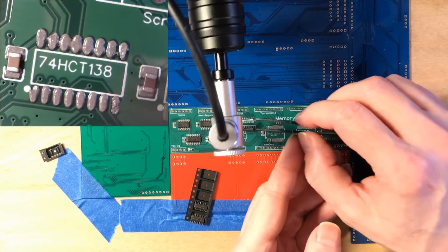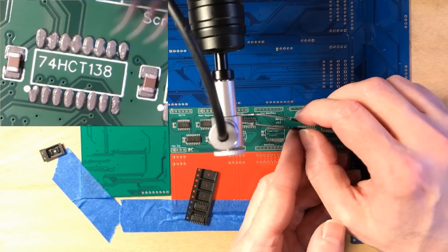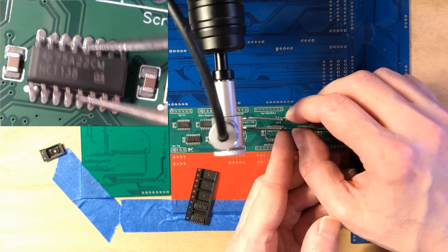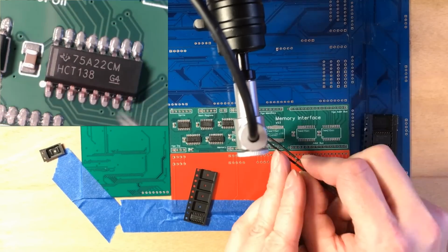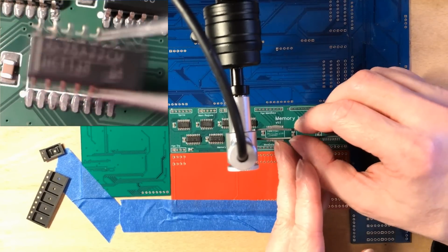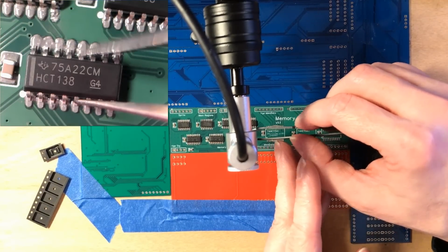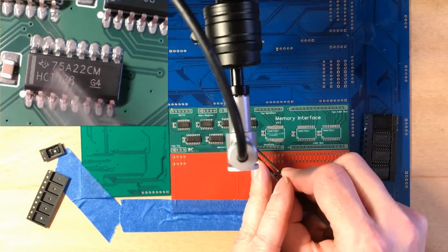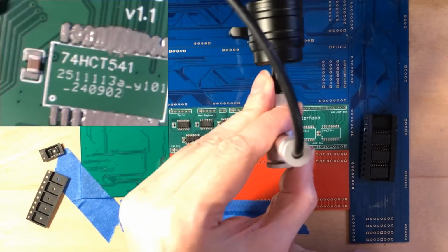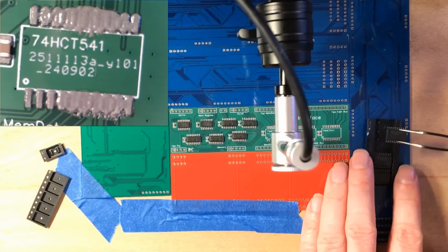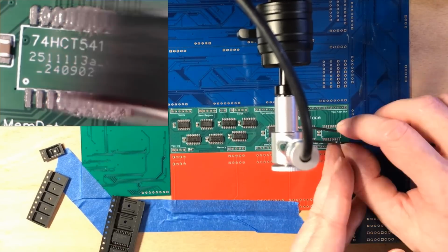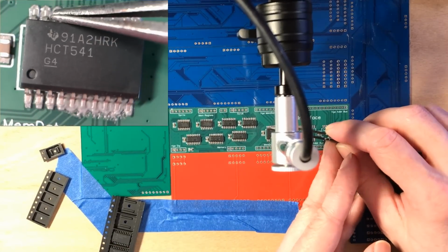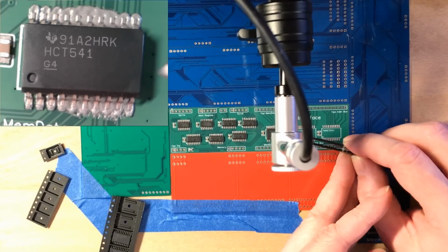By far the most common chip here is just these 138s, which are doing the address decoding. They're doing that both for the bulk memory regions for the various RAM chips in the different submodules, but they're also doing it for the individual registers in the VGA circuit as well. It's too high, isn't it?